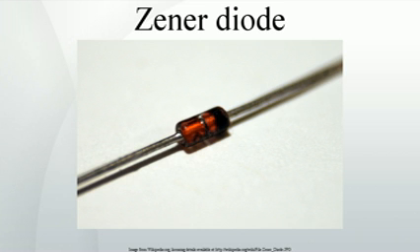For example, the common BZX79C5V6 device, a 5.6 V 0.5 W Zener diode, has a recommended reverse current of 5 mA. If insufficient current exists through D, then UOUT is unregulated and less than the nominal breakdown voltage. This differs to voltage regulator tubes where the output voltage will be higher than nominal and could rise as high as UIN. When calculating R, allowance must be made for any current through the external load, not shown in this diagram, connected across UOUT. R must be large enough that the current through D does not destroy the device.